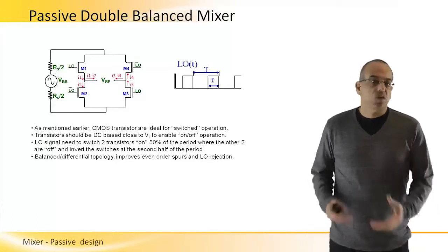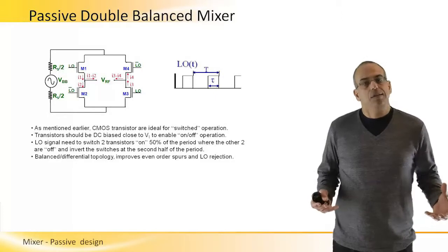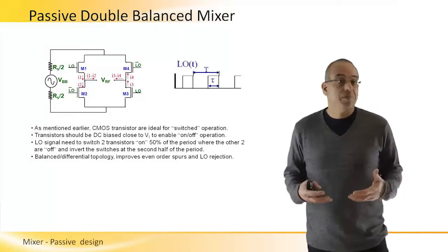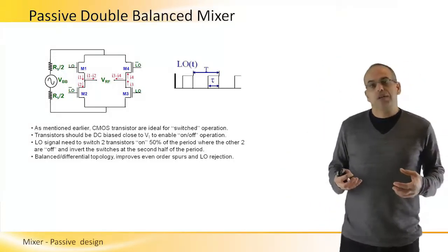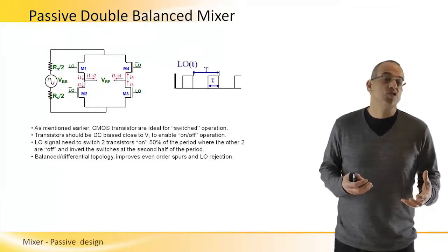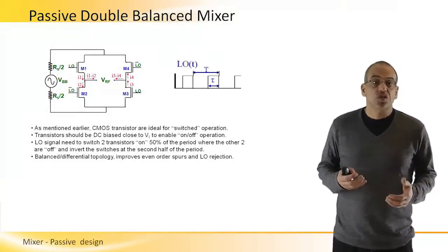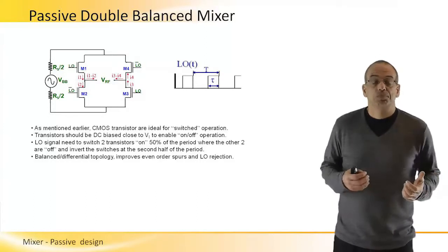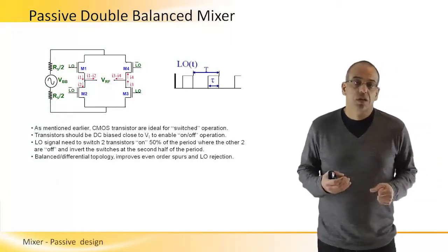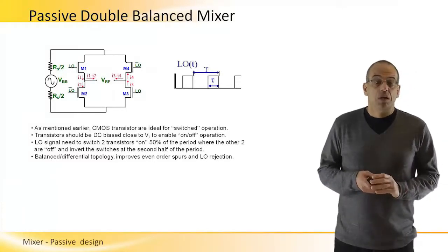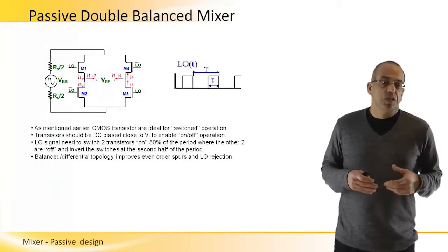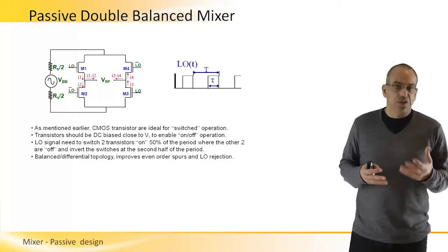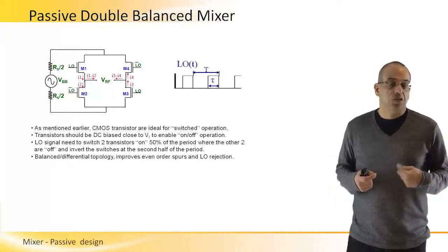Even in the old days, where people used single-ended mixers, they had internal baluns to really have double balanced performance, just to improve LO leakage performance and further reduce the even harmonics generated within the mixer. But in a balanced or differential design, we don't need to use baluns anymore, but we do take care of the double balanced topology.